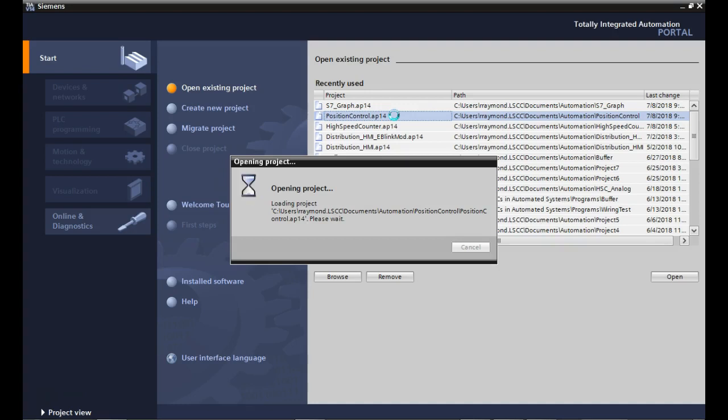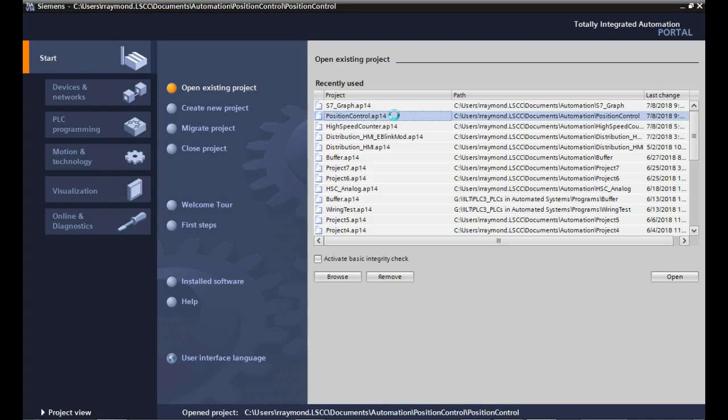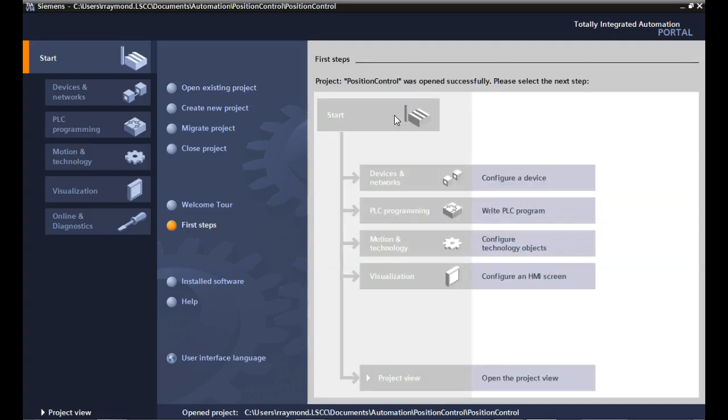What's neat about the portal? So what I would have to do if we were doing this in RSLogix 500 is take a count and convert it over to a frequency, right? You understand? So what I would do is count for 1 second, and then that would give me my pulses per second, which would be my frequency, right? Does that make sense? Yes or no?